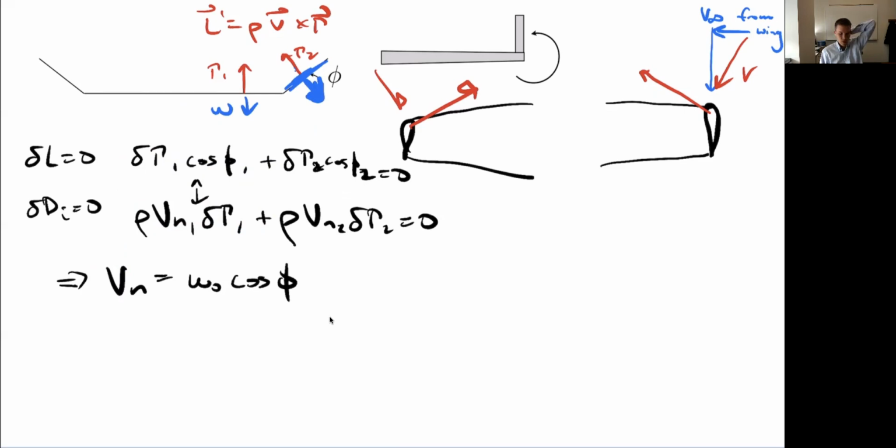So again, if the angle was 0 everywhere, flat wing, that would mean the normal wash should be everywhere constant, which is what we just saw before, right? Constant downwash along the wing. But not necessarily the case, or not so with dihedral.